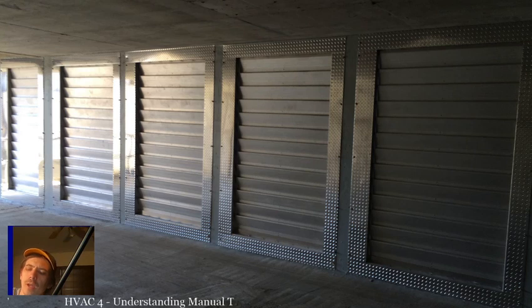If you have intermittent spark ignition or a hot surface igniter, it is generally going to be done with a flame rod. I guess if you set up a long enough sequence, you could probably prove intermittent spark ignition with a thermocouple, but I've never seen it done. It's always been with a flame sensor, because a flame sensor is a way to quickly sense that the flame is there. A flame sensor is slightly more likely to fail than a thermocouple.